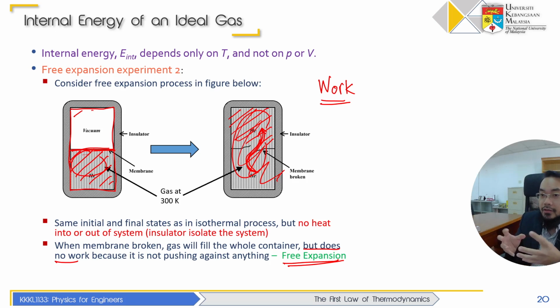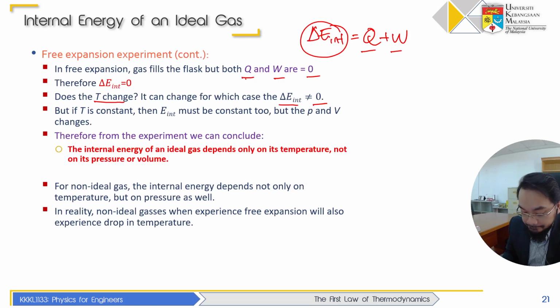That is because the gas is expanding almost freely, and the internal energy reduces, so the temperature is reduced as well. If the helium is expanding very large, not just two times but maybe 100 times, then you can have a significant change in temperature.